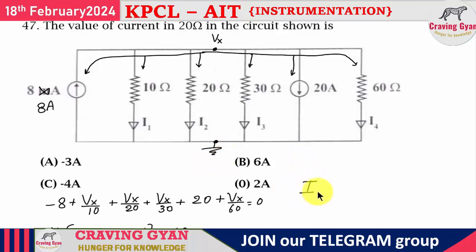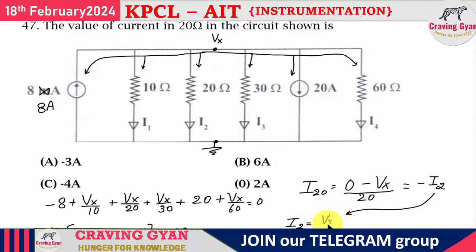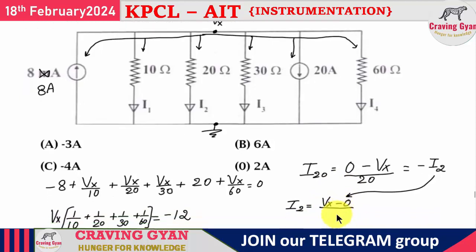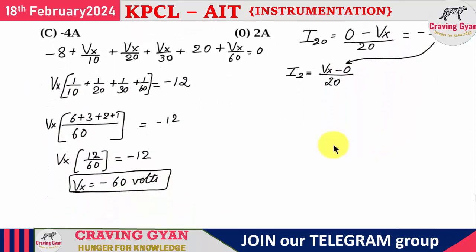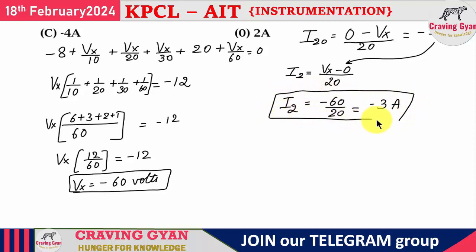So the current through the 20 ohm resistor is flowing from 0 to top, that is Vx divided by 20. This is the actual current, right? But look, this is opposite to the I2 direction. If you are having confusion, I can define I2. I2 is the current flowing from Vx to 0, divided by the resistance value 20. The value of Vx is minus 60, so I2 will be minus 60 divided by 20, which equals minus 3 amperes.